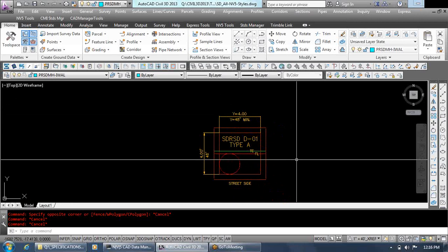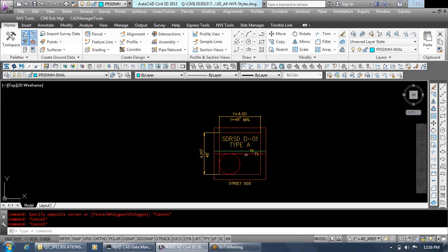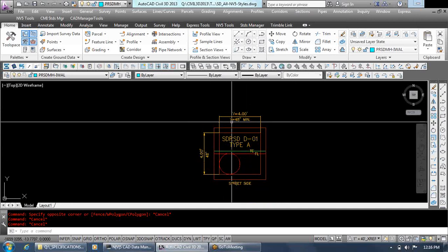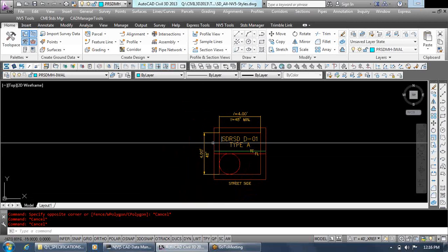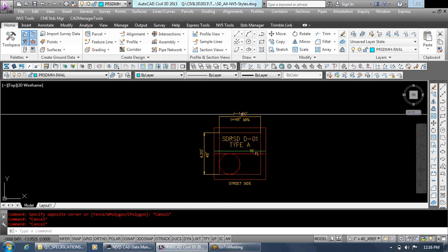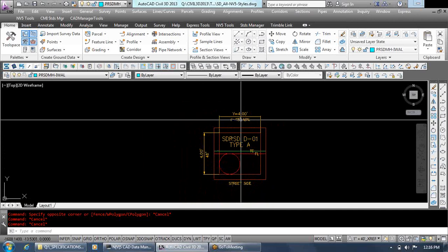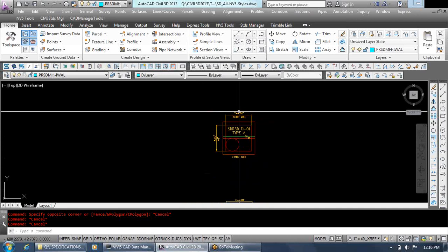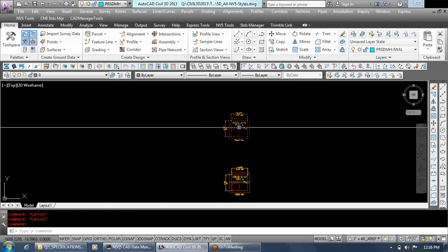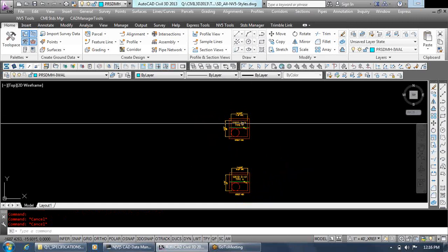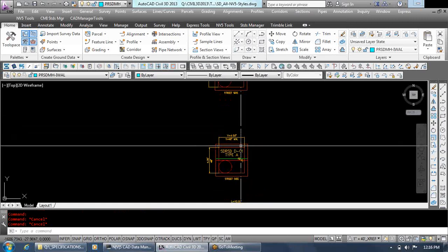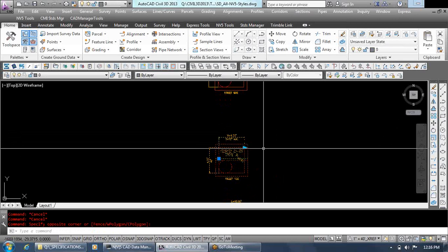What you'll notice is you have the line for the TC, you have your line for your flow line, you have some dimensions. All that stuff is on a junk layer, construction line, no plot. So none of that will show up. But it's important to know the dimensions of the blocks that you're using. So that's just a dummy block, nothing very exciting about it other than you can use it in planimetrics. But better than doing that, I would say, hey, let's use the dynamic block.